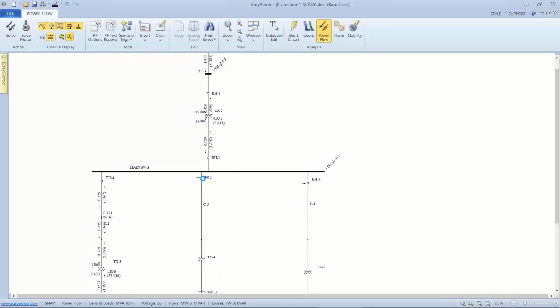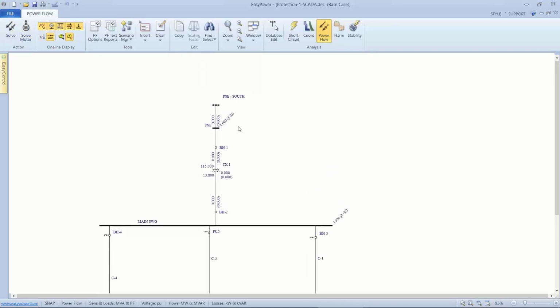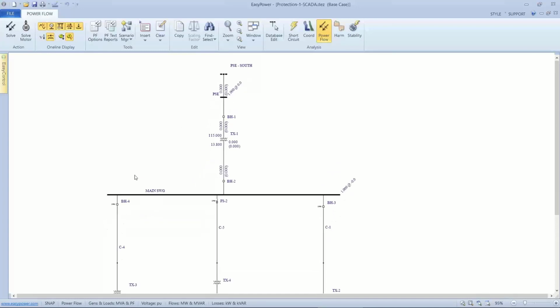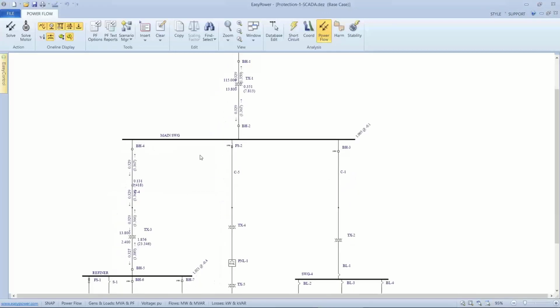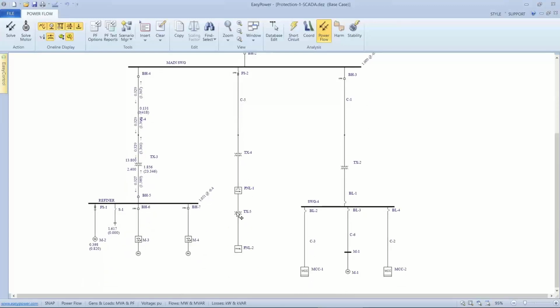It's nice to start up on the switch gear or the main, take them all off, solve. It should give me the results. Obviously there's no load, but at least it shows me some results. And then one at a time, put it online until it crashes again. And the last one that I put online, that's where my error is.